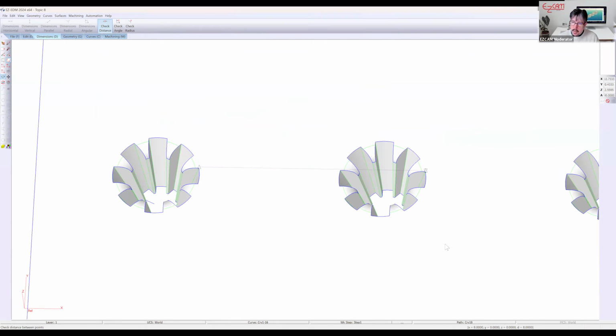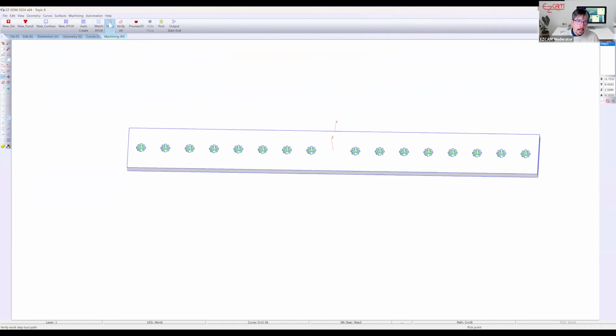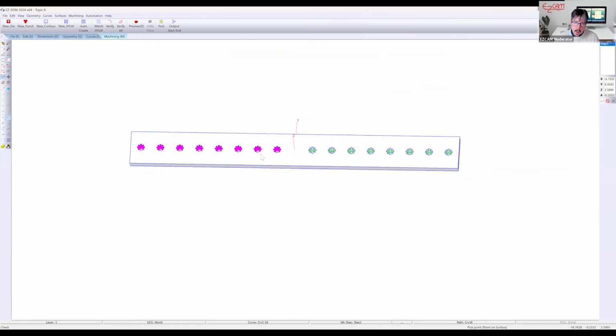That gets copied to the clipboard. It's 8 millimeters. So it's 8 millimeters in X, and we don't want to move our copies in Y. We're going to stay straight across. And our copy number is 7. Still calculating. It's complicated. So I like to think of it as a wall. If you can picture along the y-axis as a wall, we're going to take these copies and just jump the wall, give us the symmetrical order of things.